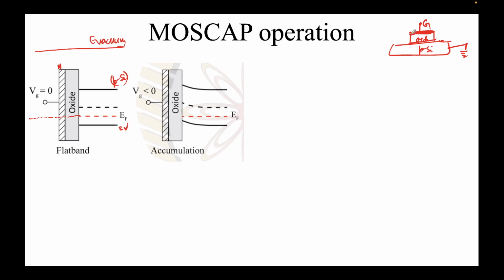So now what's going to happen, you can simply assume, again, no current can flow through that, but electric field lines can still penetrate. So if you apply negative potential to this, it will repel the holes that are here. Sorry, it will attract the holes. Negative potential you're applying, it will attract the holes. So you can see what's going to happen as compared to the bulk. This is the bulk region over here. Let's say this is the bulk, and I'm calling this region the surface. Why call it surface? Essentially it's the oxide semiconductor interface, which I will interchangeably call the surface.